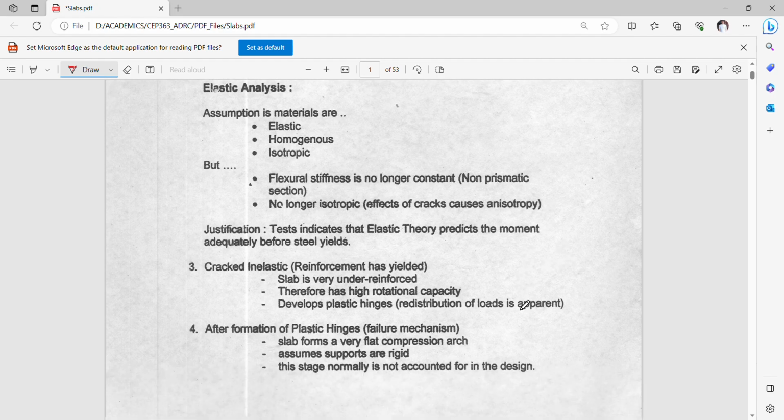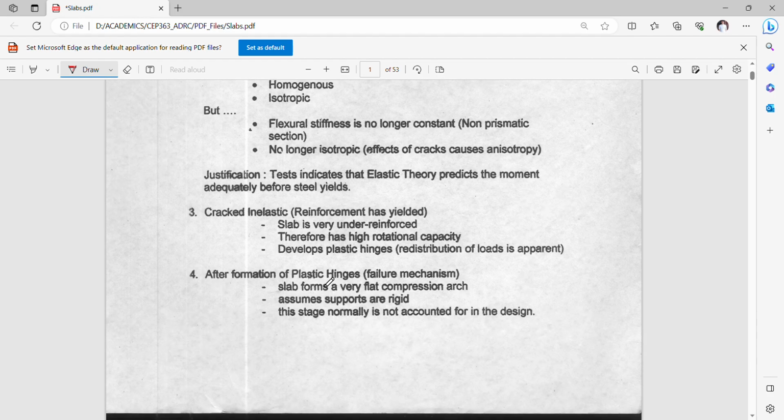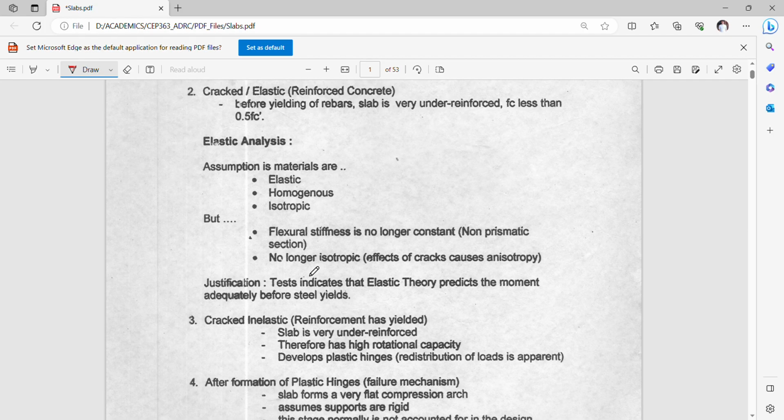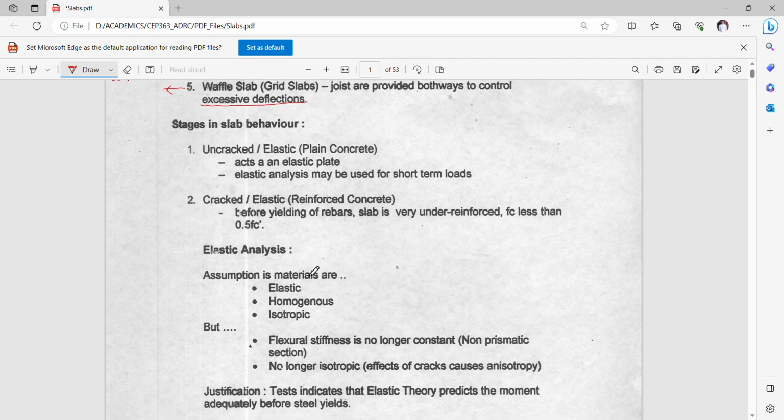In beam behavior, this plastic stage is normally not included in basic discussions, but for nonlinear analysis, the beam behavior also has this stage wherein the formation of plastic hinges is expected, which allows the member to behave beyond the elastic range, into the nonlinear inelastic ranges.